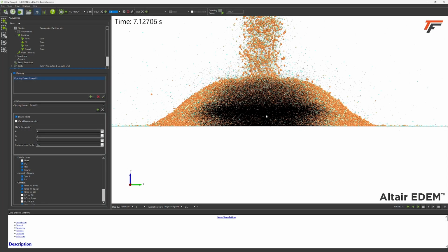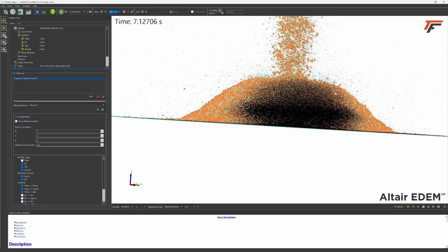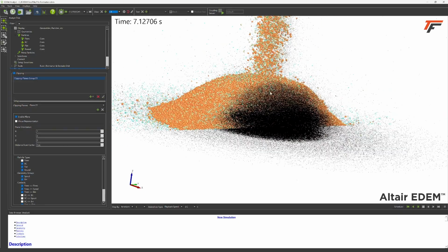We did some research a few months ago, and we actually found out through some testing we did in the field and some airflow models that we ran based on these simulations that the core of the bin actually has 67% less airflow.